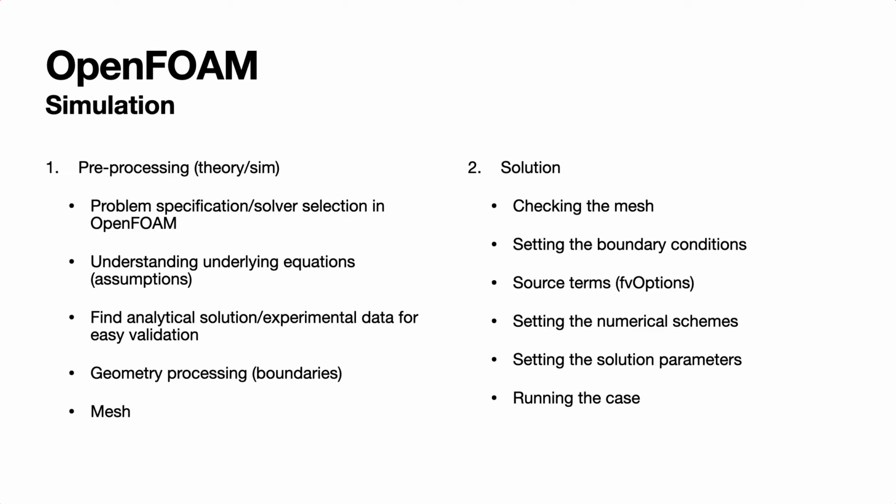We still need to process our geometry so that it can be read inside the code, and then we need to create the mesh. On the solution side, once we have the mesh, we need to set the boundary conditions, we need to set the source terms, as well as some numerical schemes for divergence, and then the solution parameters for solving the algebraic equations, and then we can run the case.